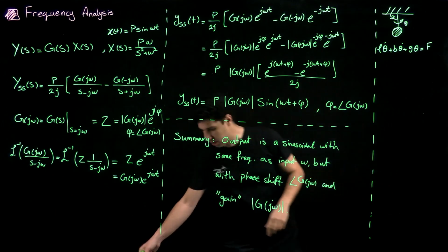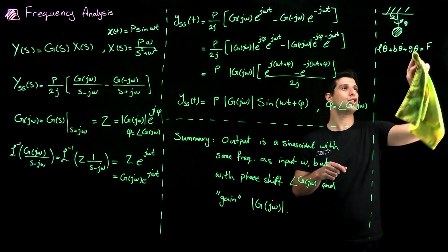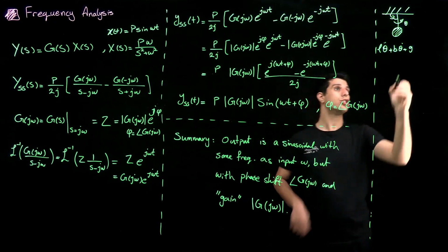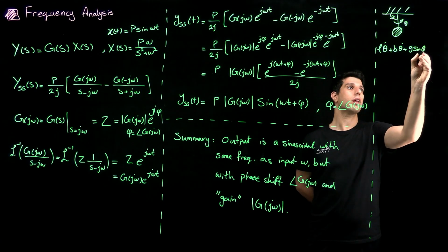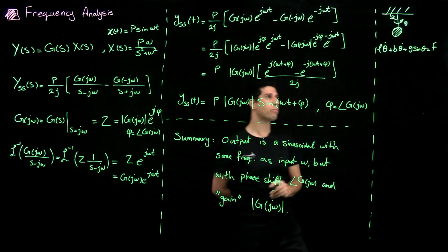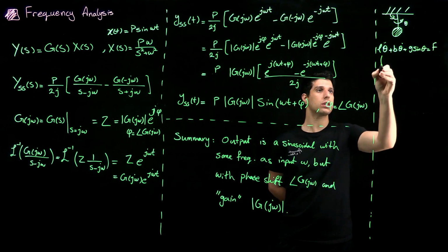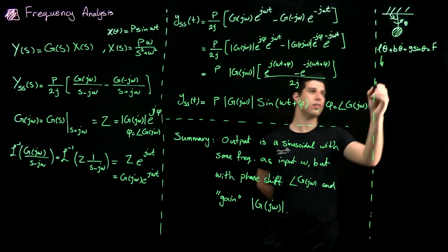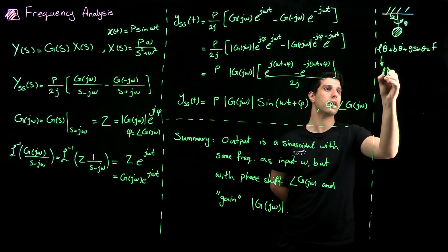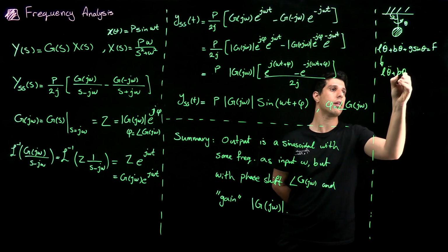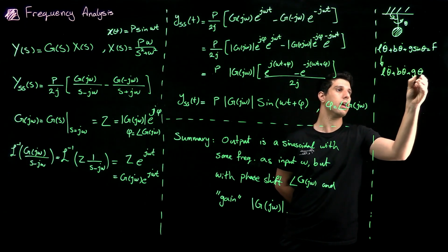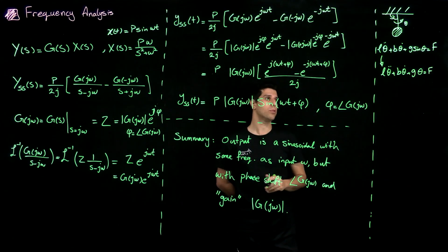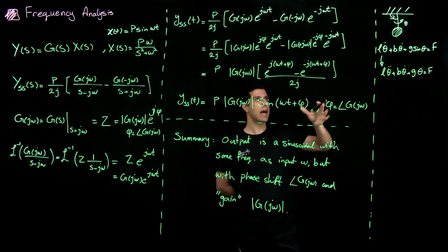And now, because I cannot easily work with a nonlinear system, let's linearize it. The linearized version is L theta double dot plus B theta dot plus G theta equals F. And F, you can think of it as a torque that is acting on this pendulum.